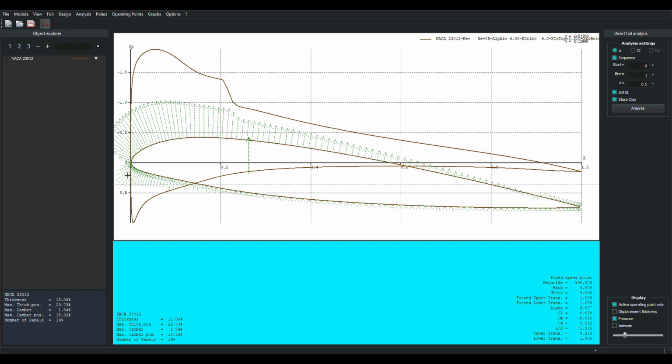And we have to get that flow back to free stream conditions in terms of speed and pressure. So the pressure going off the trailing edge here has to be essentially the same as what came in at the leading edge. If it's not, you get a bunch of turbulence off the back end of the airfoil. So adverse pressure gradient, the pressures are increasing. Anytime there's more pressure in front of you than behind you, that makes it hard to move forward.